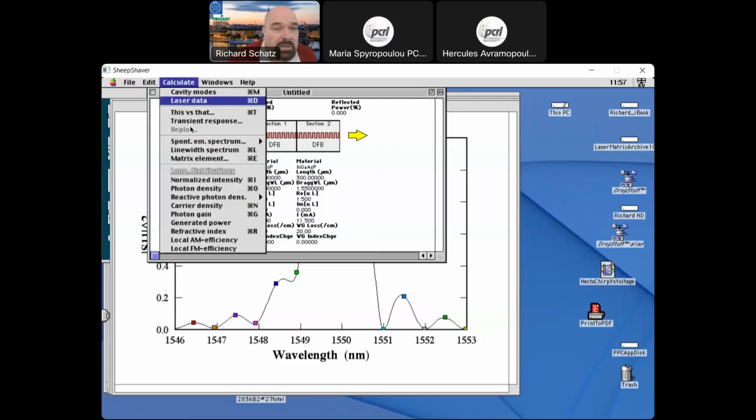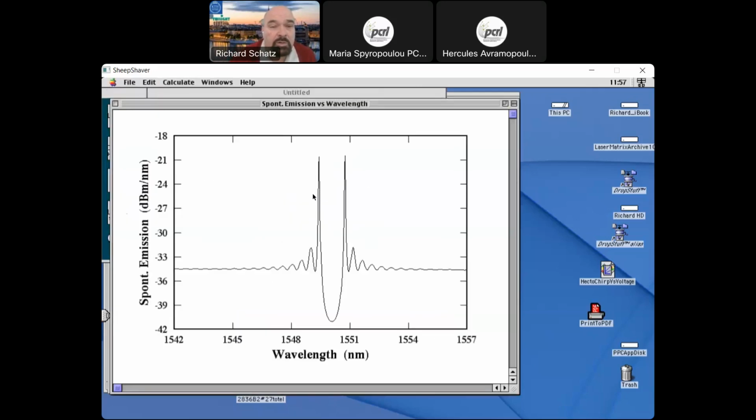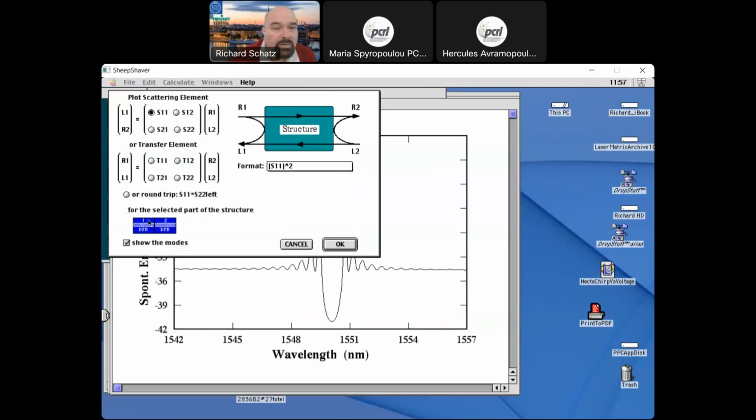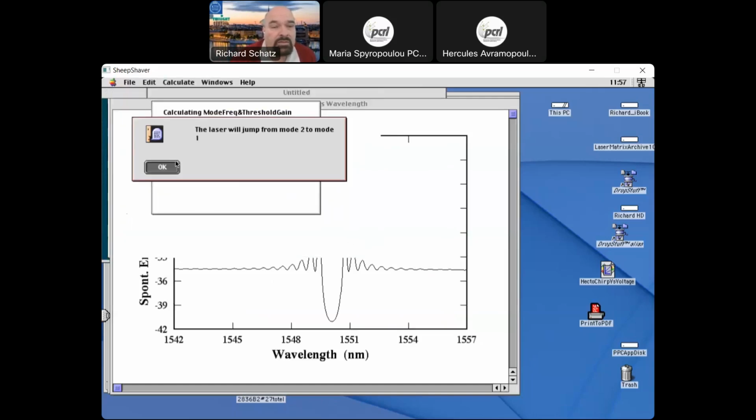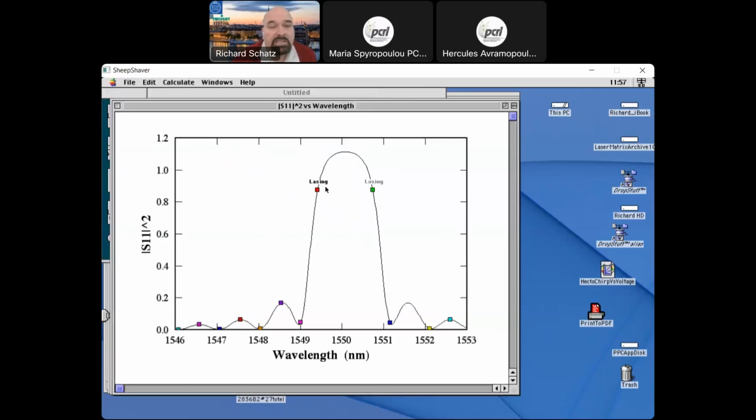So here again, we can look at the spectrum first. So we see this, that it still has 2 modes, just. You see, it has 2 modes here. And to understand that, we can look at the reflectivity spectrum then of this. So I look with reflectivity here, and then you will see that, yeah. You see that the laser either lases on this mode or on both modes. So you see we have not a good modal selection here, we have a bi-mode laser.